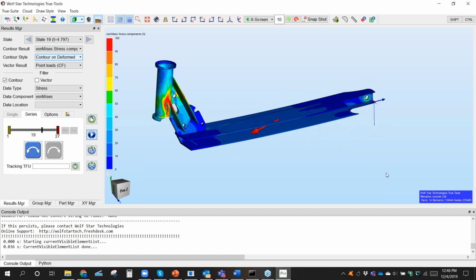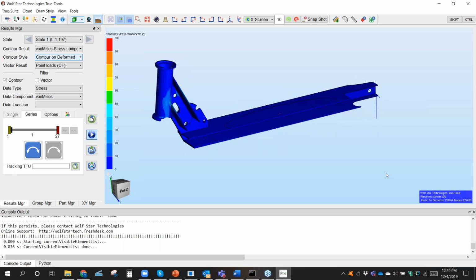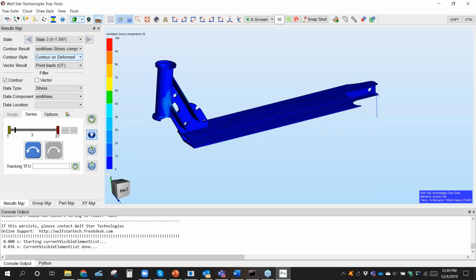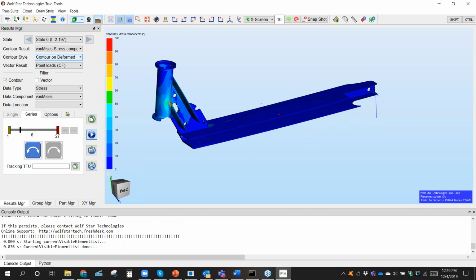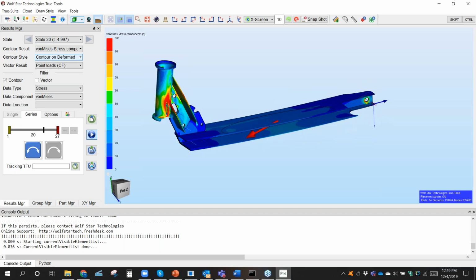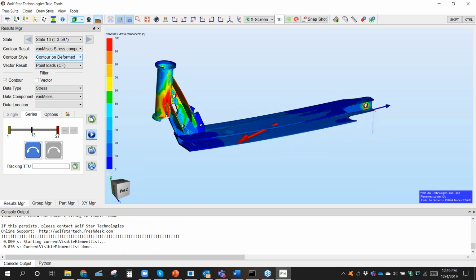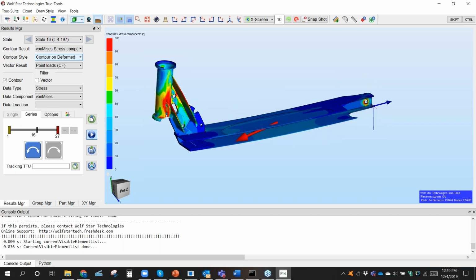Okay. Thank you. One question also deals with the thermal loads. Can TrueLoad combine thermal mechanical loads in one simulation? Yes. So basically, you just need to put a unit load on your model, it will be a unit thermal load. So it might be a unit load of 10 degrees or 100 degrees. And then we're going to scale that unit load case up like we do any other load. TrueLoad is really just looking at the strain response based on whatever loading you've put on the model. So whether that's a thermal load, a pressure load, or a force load, we're just scaling that up and down. So we'll just mix it in like anything else. Perfect.